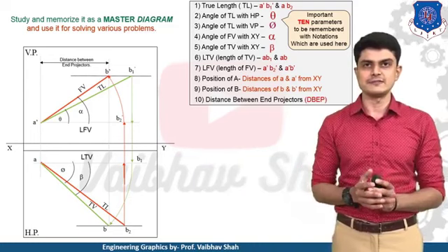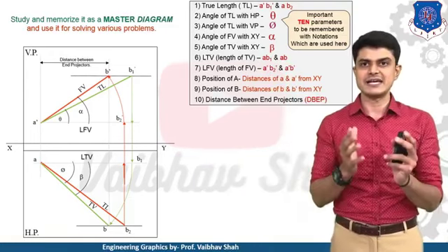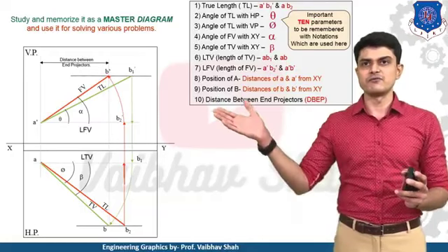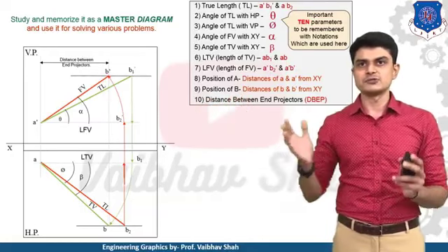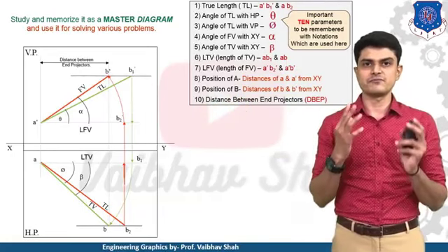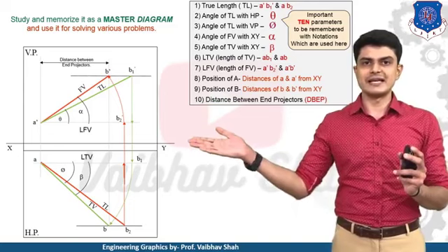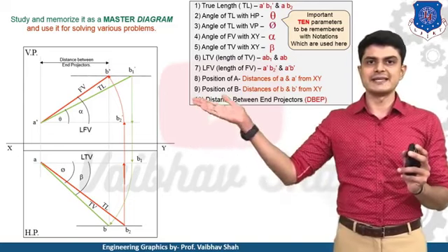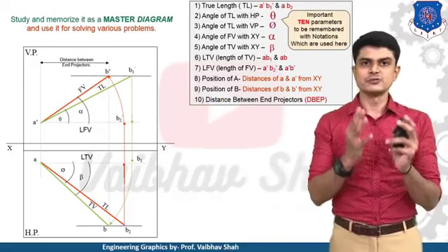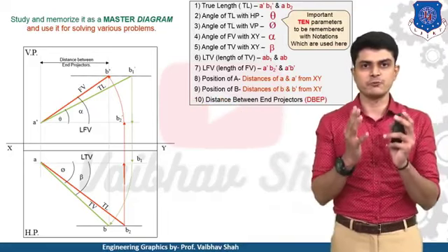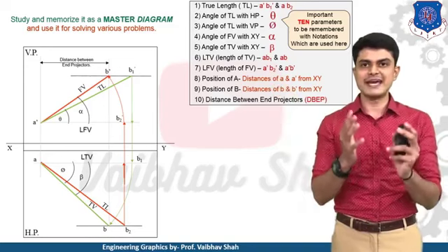So this will be your final answer. Then after you will be having the angle of front view with XY, which is alpha. So here, the angle of front view, let us observe A dash B dash, which is what? Alpha. So there are two possible cases. Front view would be either a horizontal line, as you can see, length of front view, or front view would be at angle alpha, and front view is always denoted by dash, so you need to draw your front view from the dash point only.